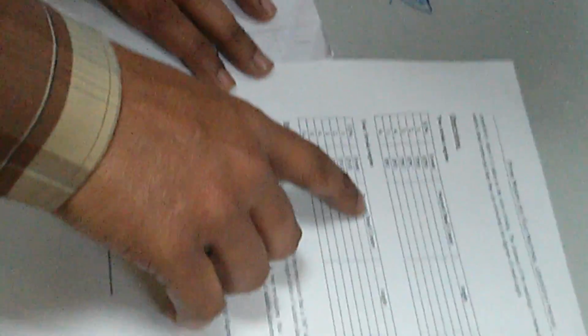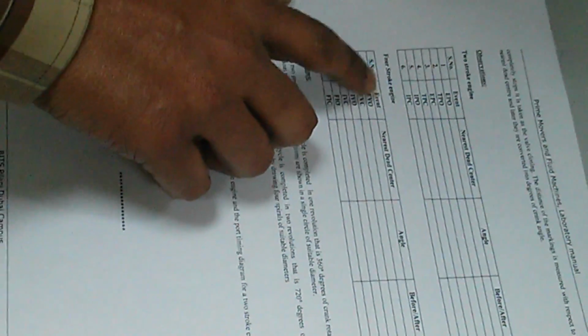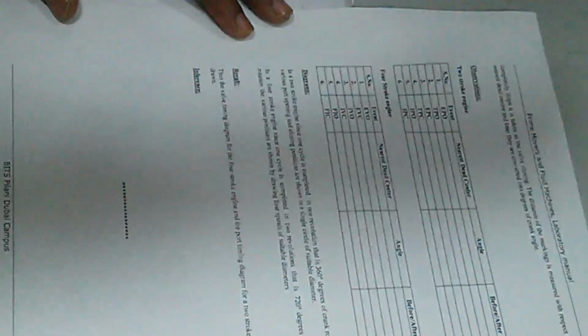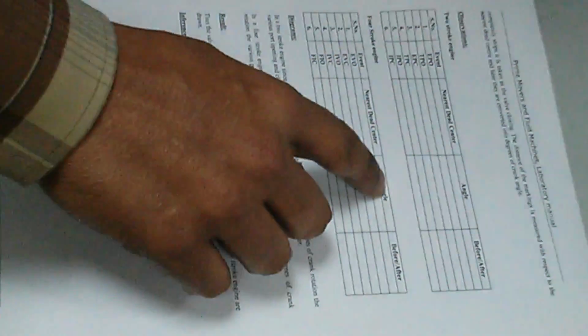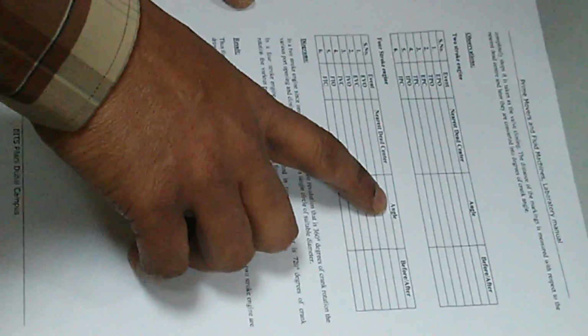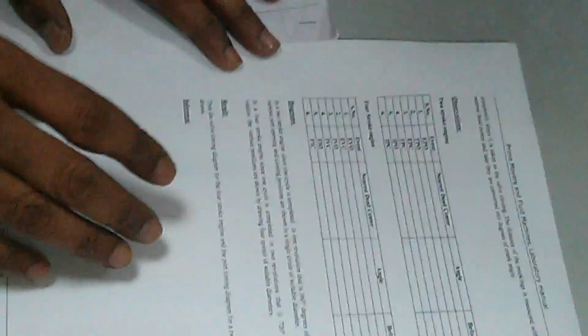And I also need to mention, for each event, the nearest dead center: whether this event is happening closer to the TDC or closer to the BDC. I need to mention the angle with respect to the dead center, how many degrees. I can measure that on this graduated scale and mention it. And I should also write whether this event is happening before or after the dead center.